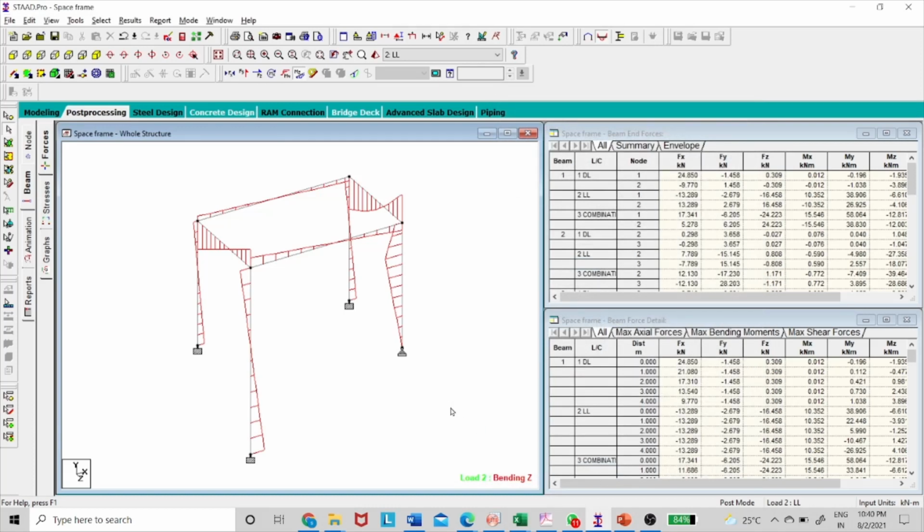Right, so basically for beams we will consider mz is the most important, because the bending axis will be z. So it all depends, generally the modeling, loading, etc. will be given as per the global coordinates, that is xyz, whereas the STAAD will present the results in the local coordinates.